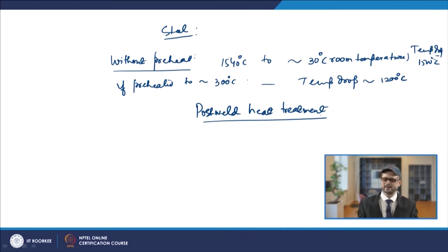But when we look at the post weld phenomena, there will be chances of the formation of residual stresses while cooling. In those cases, if the residual stress levels are at a higher amount, that may lead to a decreased service life of the component. So, the welded component may fail. So, post weld heat treatment is mostly for stress relief treatment.